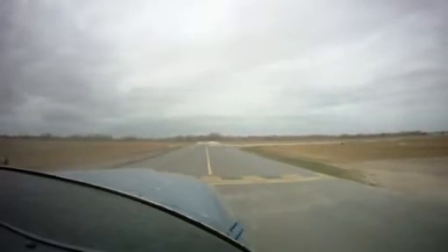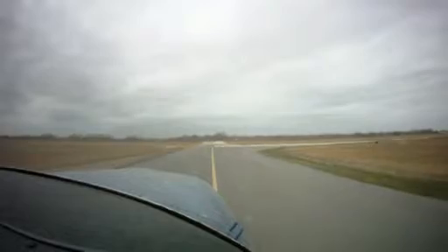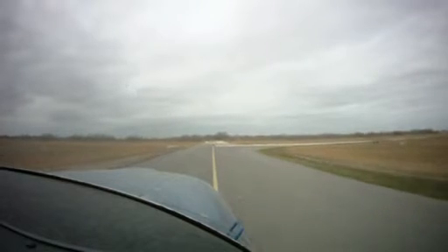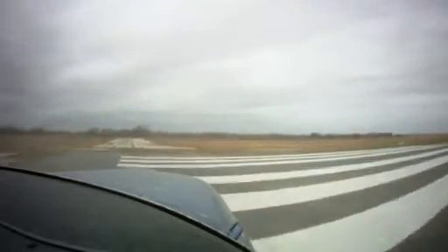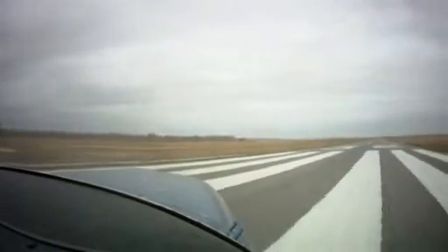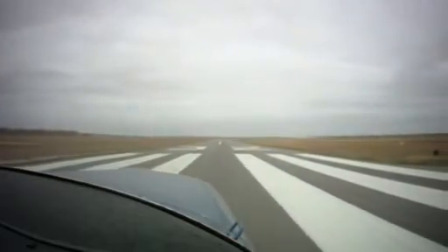The first thing that I want to do is align myself with the runway. So I'm going to go ahead here. Airport traffic November 65328, position and hold runway 32 Edinburgh. So I've already advertised my intentions to everyone around here. I'm making sure that nobody's coming from the left, nobody's coming from the right, nobody's coming from the center, and we are clear to access the runway. The first thing that I need to do is to maintain the center of the runway with my nose. So I'm going to take my time over here and get on the center of the runway. And you will notice in a moment how the wind is coming very strong and cross from the right.